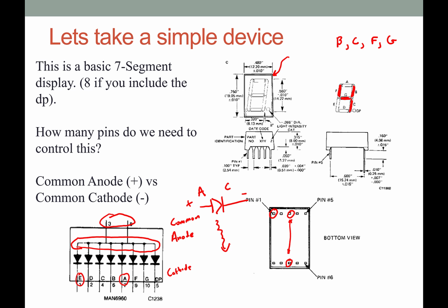As I increase the voltage, I'll finally get to a spot where I see that the LED emits some brightness that I can actually easily tell that it's lit. And from that point forward, what could change is maybe how bright it is, but in general, once it's on, any increase in the positive voltage from here to here is not really going to change it. Obviously, you could get too high a voltage and maybe you would break the diode, but in general, what we think of is we're going to put this positive voltage across the diode.